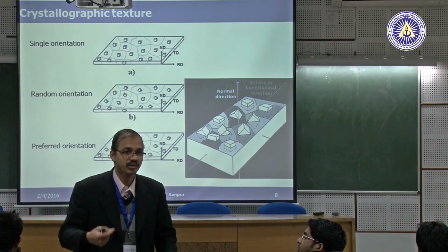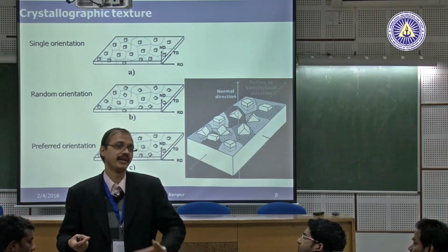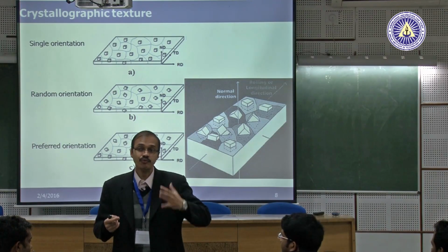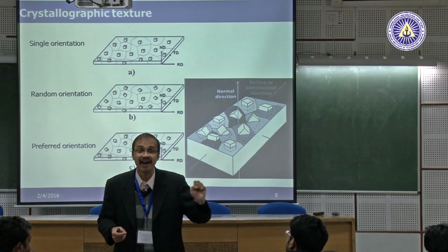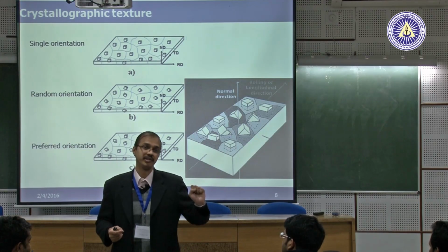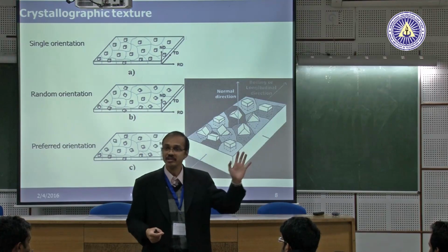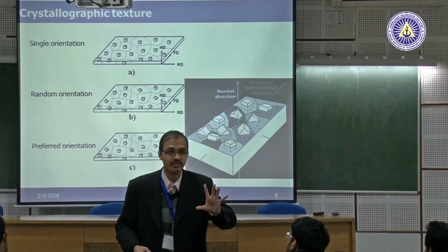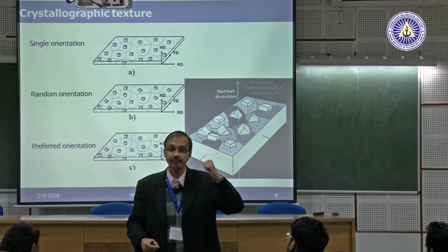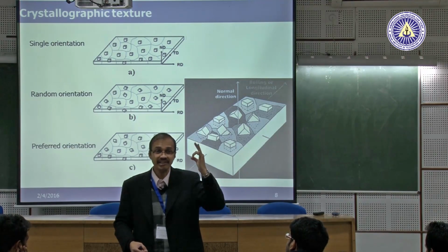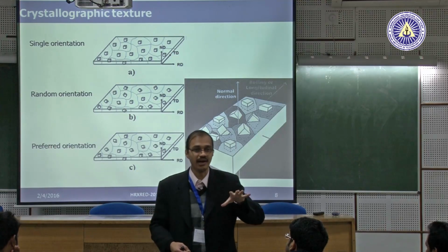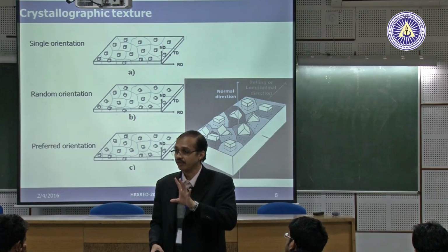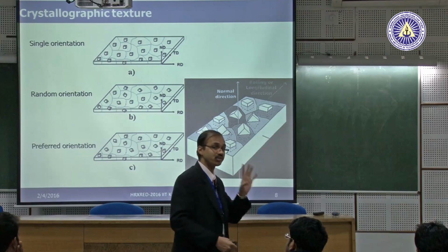Okay, so there is something known as the paint bake cycle and so on and so forth. You do a hardening cycle and so on. So this is the entire philosophy that you want to engineer the properties. You need a handle to play with the properties. And if you understand crystallographic texture, see, microstructure everyone knows, you play with the grain size or you induce some element, play with the chemistry, that you can do. So texture is also an important parameter. You may not get a 3 times change in strength or elastic moduli, but you can get at least 50 to 60% change. That itself is quite good, right? So that is the entire idea of crystallographic texture.